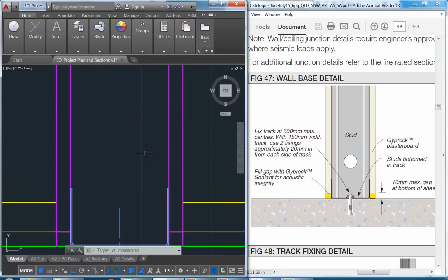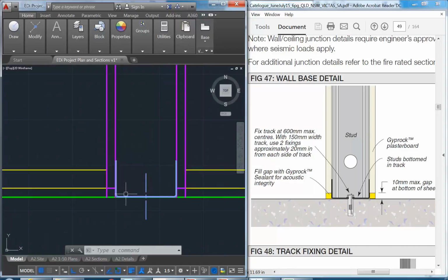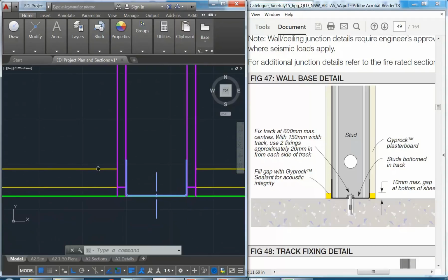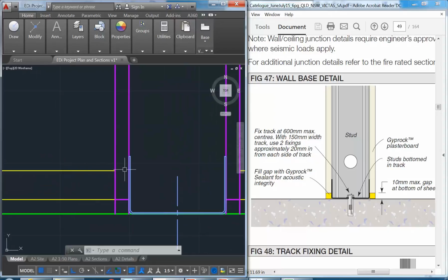So that's pretty much it except for the skirting. So you can add the skirting over the top, and that'll depend on your chosen skirting detail. Okay, so it's important when you put the skirting on that, well actually, you've got a few ways of doing this. You could extend the floor lining to the stud framing and then have the plasterboard finish above that, but it's actually okay to do it like this. You can have the plasterboard go in behind the wall lining and then the skirting would simply sit above.